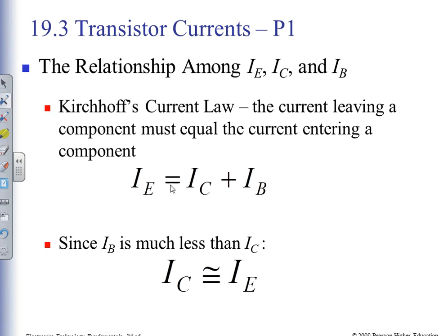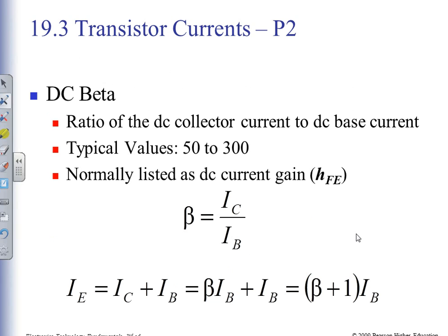All right, so now we look at relationships, and we see that Kirchhoff's law says whatever the current is at some node, it has to be whatever's coming into that node equal to whatever's going out. So the summation of currents at a node must be 0. Therefore, the current at the emitter has to be the collector current plus the base current. The base current is a whole lot less, so sometimes we just ignore it. It's two orders of magnitude less if my gain's 100. So in some calculations, we can just ignore it altogether and be perfectly happy. We're perfectly happy all the time, right? Yeah, so ignoring things makes us happier. There's my beta plus 1.